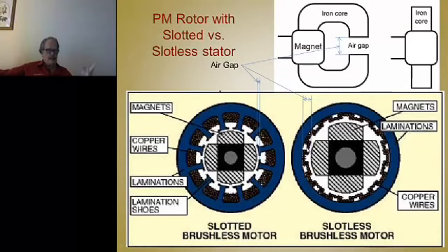The current's the right polarity that's going through that coil. There's a force on that wire. But the stator can't rotate, so according to Newton's law, there's a reacting force against the rotor. So it's the rotor that moves, and the field moves with it. So that's why you got to commutate. As soon as it moves over here, I've got to change the polarity of the current in the new coil that's under that pole to keep it going. So this one's attracting and that one's repelling.